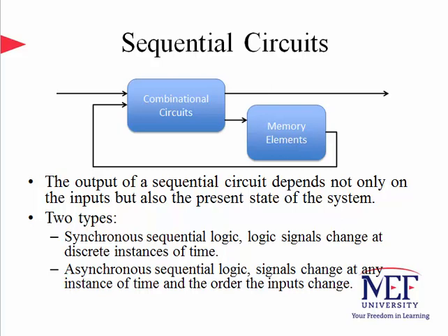There are two types of sequential logic. One of them is called synchronous, the other is called asynchronous logic. In this class, we'll only dwell on the synchronous type, and we may have some discussions on asynchronous logic sometimes, but majorly we'll be focusing on the synchronous type, in which the signals affect the storage elements at only discrete instants of time. Synchronization is achieved by a clock generator, which generates a periodic train of fixed clock pulses. Clock pulses determine when computational activity will occur within the circuit.